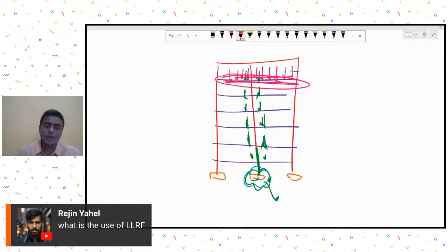So horizontal elements will be designed for full live loads, but I'm talking about vertical elements where the effects of live load are accumulated over the different floor levels. There we are raising this question that the chance that every slab level within the tributary area of this column or vertical member is loaded to its full live load intensity is quite rare, and therefore I introduced this concept of live load reduction factor.